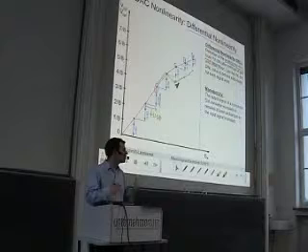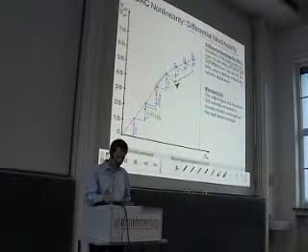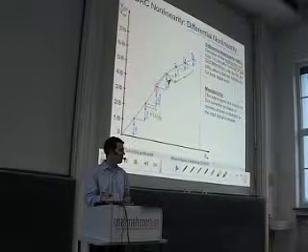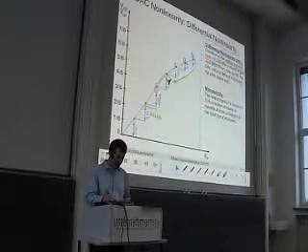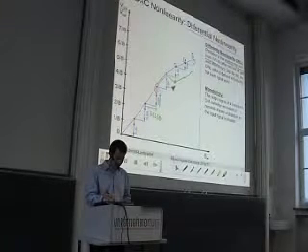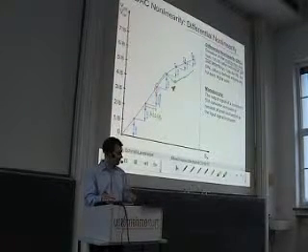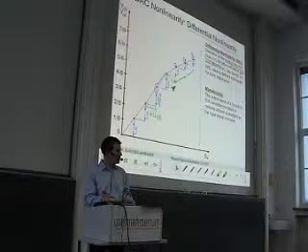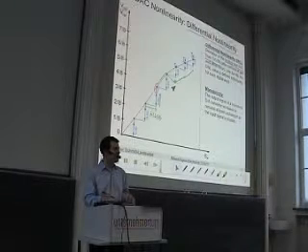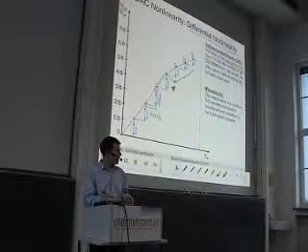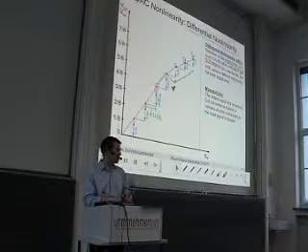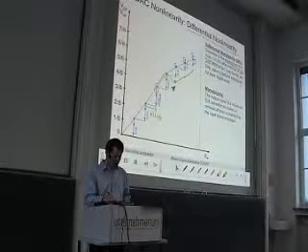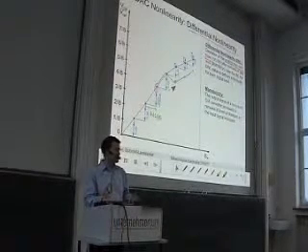So if you talk about differential gain or something like this, then you see that here you get a negative slope, which can be a problem on system level. And we will see that there are circuits realizing DACs that are robust against non-monotonicity. This is circuits where non-monotonic behavior cannot occur, and there are other circuits that are susceptible to non-monotonic behavior. And I will come back to this point when we discuss these circuits next week.